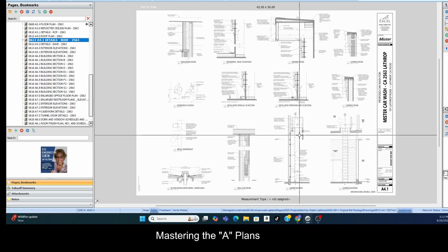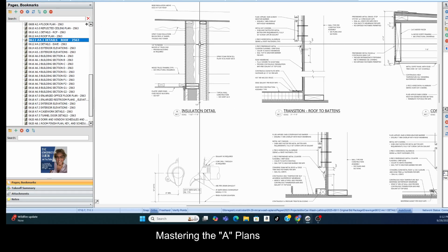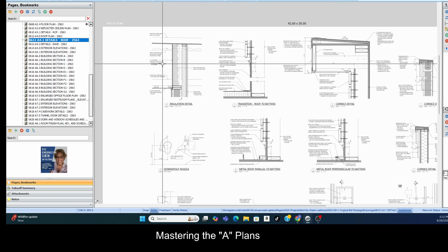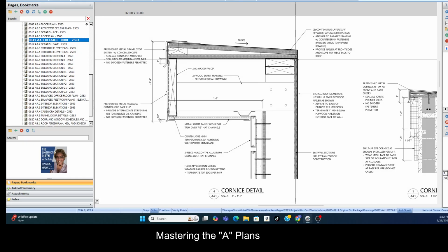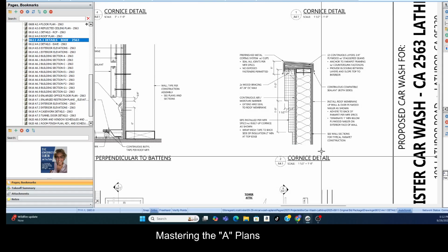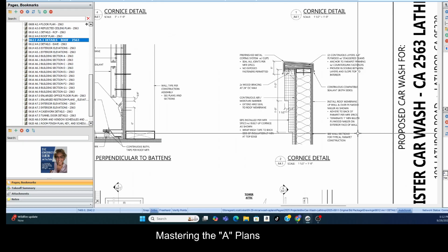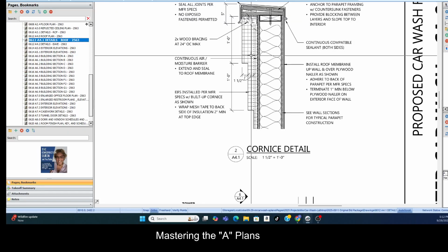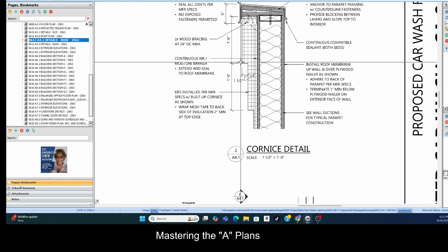And let's look at a lot of roof details. Okay, so the insulation, a lot of roof details. And really all of these come from the plan view where we took the linear measures. Right, section views, that's what section views show us. If we cut there at the building, this is what the interior construction looks like. Well, at the cornice, we've got the eaves.